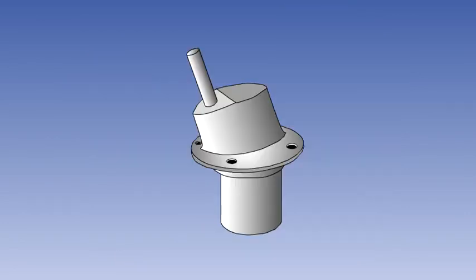The Rosemount ice detector is another mechanically operated accretion type of detector. It consists of a short cylindrical probe positioned in the airflow, mounted on a vibrator housing which vibrates the probe axially. If ice builds up on the probe, the added mass reduces the frequency of the vibrations. When the frequency falls to a predetermined level, an ice warning is given.